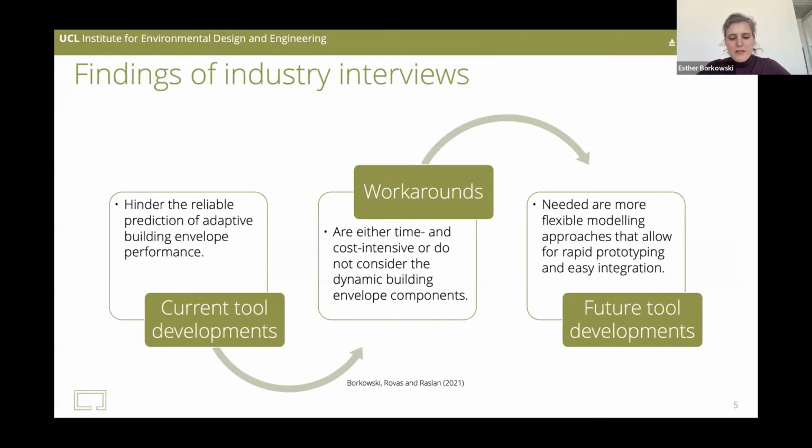And since the development of the modeling approach was based on the findings from the interviews, let us quickly look at the results. I found that current building performance simulation tools hinder the reliable prediction of the performance of adaptive building envelopes. This is because the accurate representation of the level of detail of adaptive building envelopes is perceived as challenging. The workarounds applied in response to these limitations are either time or cost intensive, or do not take into account the dynamic components of the building envelope.